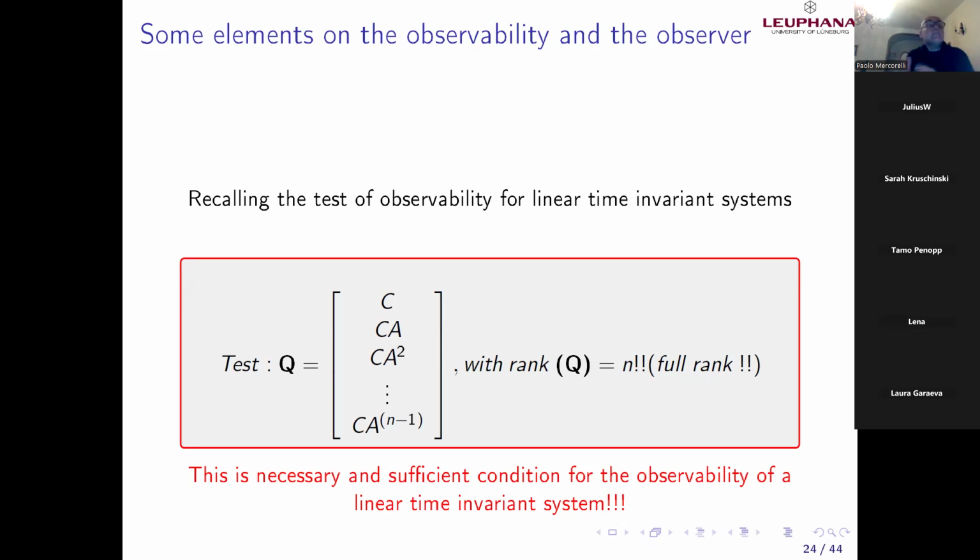This means we have in this system two kinds of energies. Do you remember in the DC drive, the model for engineers is easy, but also for the other students, I tried to clarify that we had two kinds, or three eventually. But let me consider the reduced system. We have two kinds of energies: electromagnetic energy because of the coils, and kinetic energy because the motor runs.